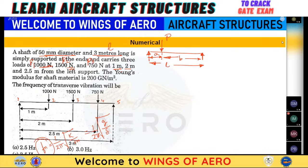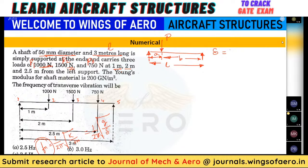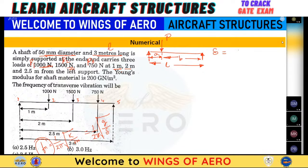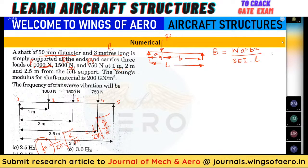Now you have to use the bending moment formulas that I have shared with you. What will be the deflection for this condition? Do you remember? Can anybody say about those things? The deflection is W A square B square by 3 EI into L. This is the formula.